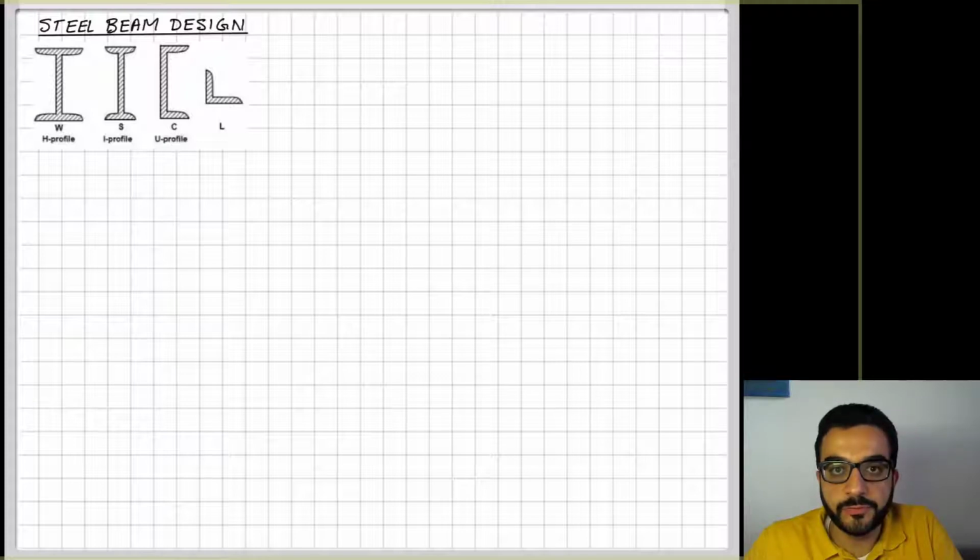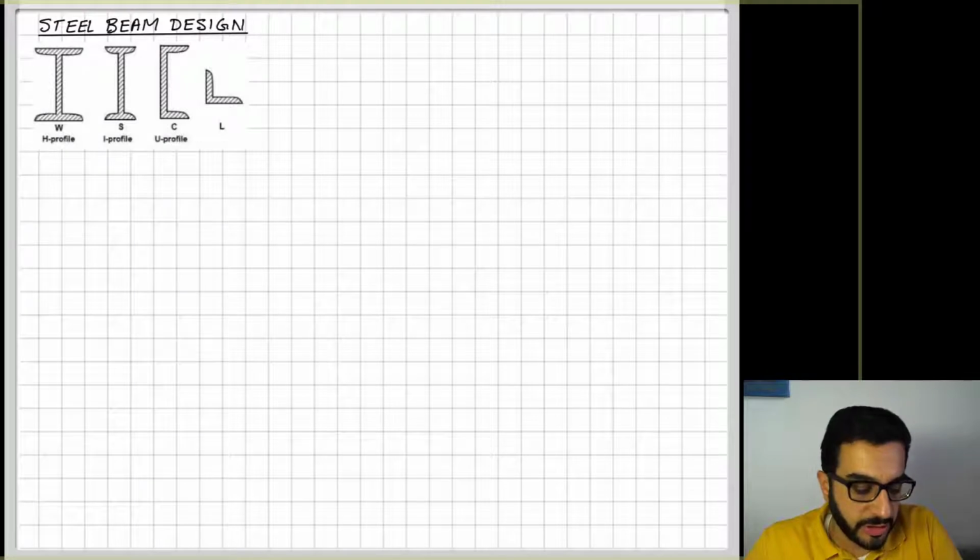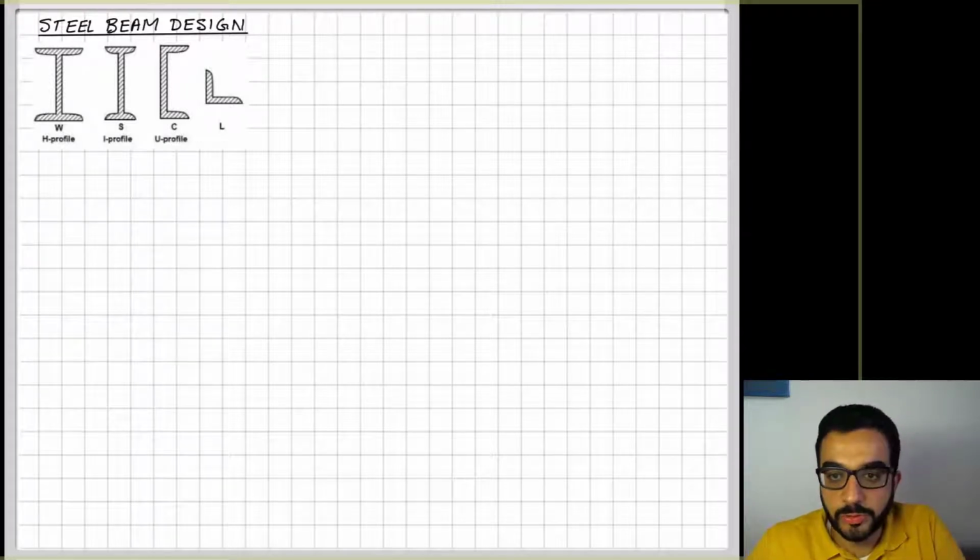Unlike wood beams, steel beams are made of standard sections. With wood, we can add sections or parts and have flexibility with the wood section. There's glue laminated timber, so you have flexibility in shaping the cross section of your member or beam. For steel beams, you have flexibility, but still your building blocks are standard. Your building blocks here are standard cross sections that everyone in the industry knows, like their names.